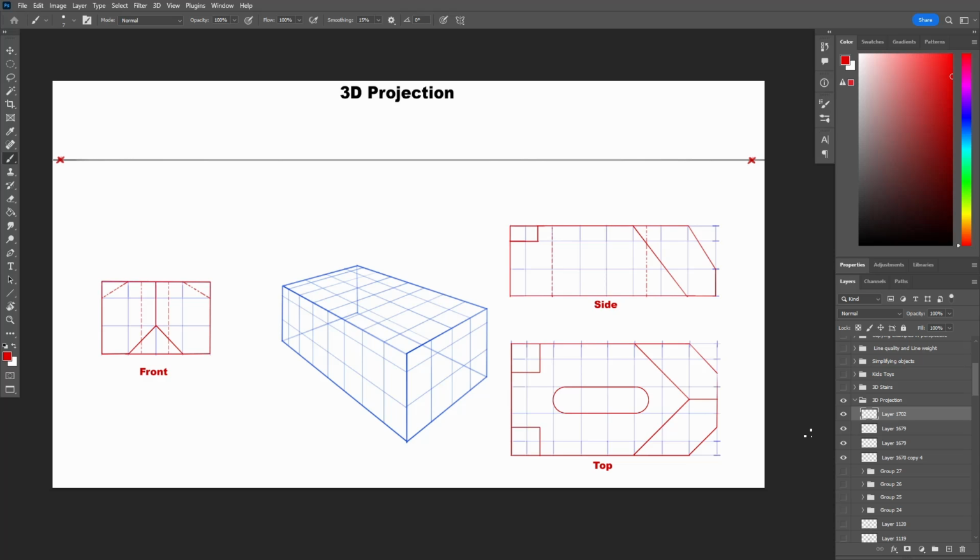So let's dive in. So here we have a complicated shape with lots of slopes and intersections here and there. I went ahead and drew the segments unit on the box already, so we start right away with the drawing. You should be able to do the divisions on the box by heart by now, since we did it a lot in the previous lessons and examples. So let's decide which side we start from. The side view seems simple. So let's start with the hole in the top left, 1 unit wide and half a unit in height.